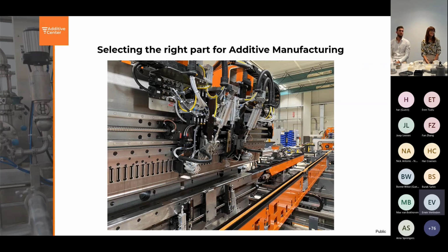Yeah. So you guys need to understand the technology enough, so at the beginning of the design process, you can make the right judgment. Am I going to mill this? Am I going to sheet metal this? Am I going to print this? I think that's important for you to keep in mind when looking at this.